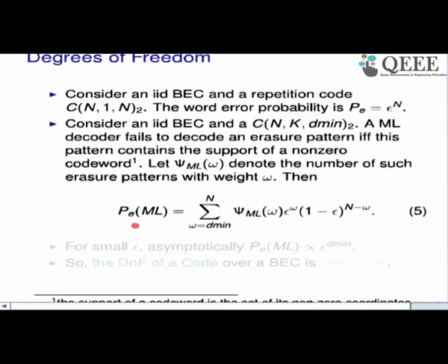It's widely used in LDPC decoding because assuming an erasure and decoding is much simpler, it is polynomial time decoding in turbo codes and LDPC codes, while assuming it to be in error is exponential. Because of that, this erasure channel has gained significant importance.